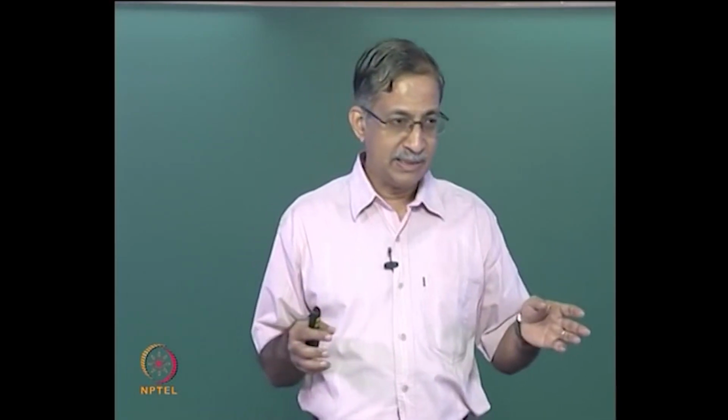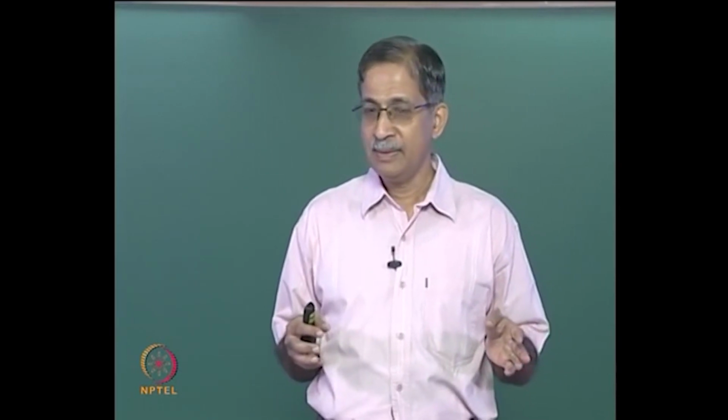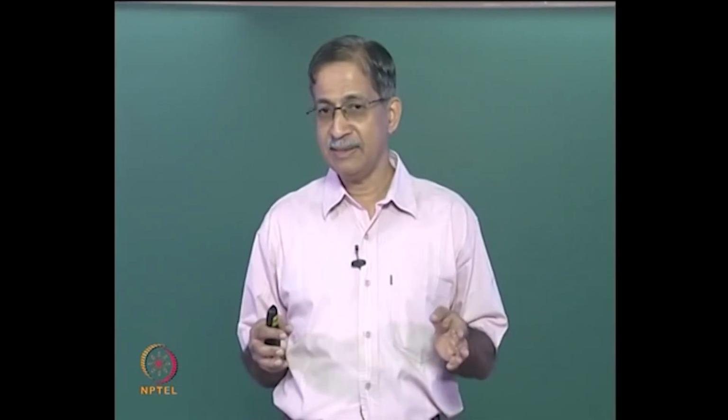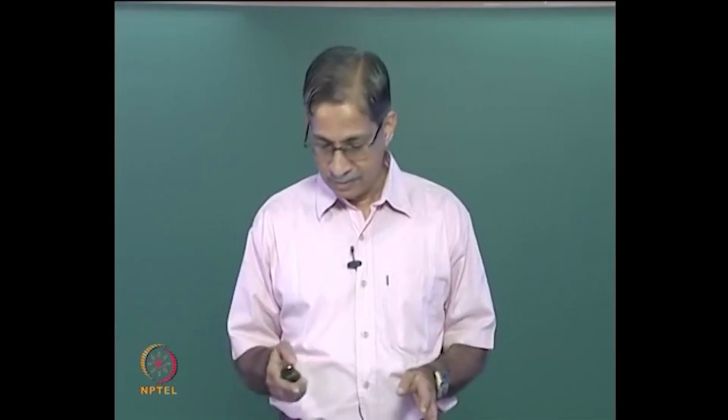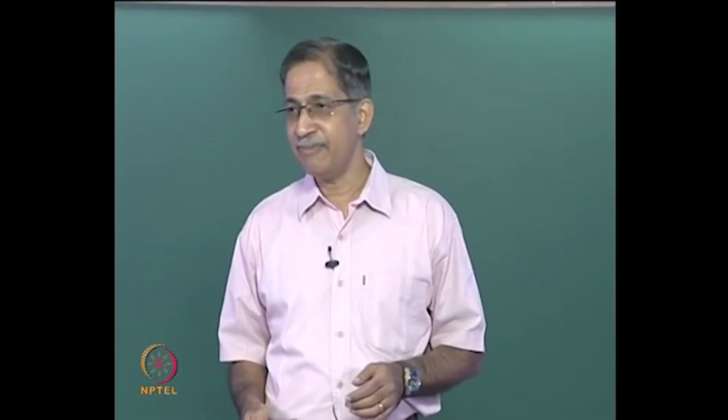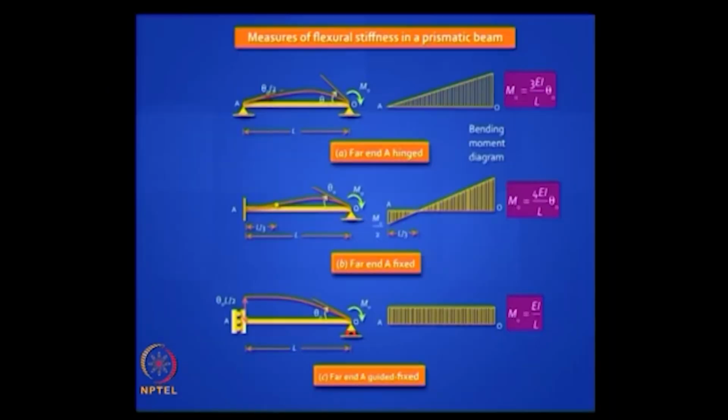If the far end is simply supported, it is hinged, then it is 3EI by L. If the far end is fixed, it is 4EI by L, clear? Okay. Let us take this one step further. Let us say the far end is a guided roller support, okay. If the far end is a guided roller support,